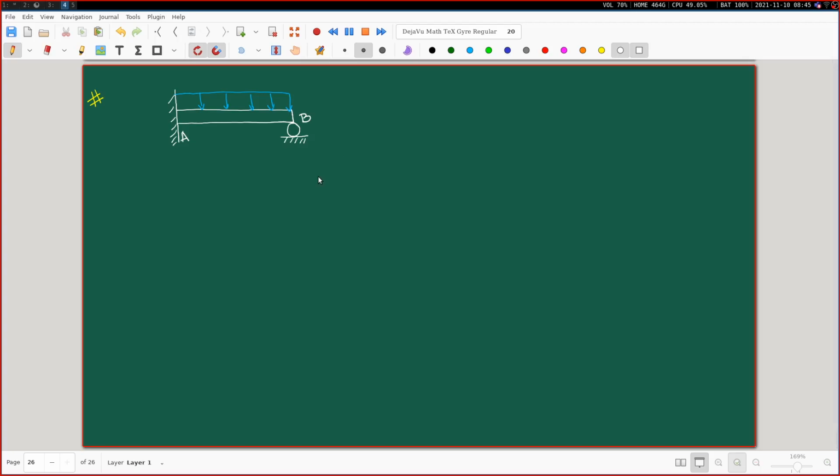So, what he said is like this. Our interest here is to find out the reaction force at this point. I mean, we want to find out all the reaction forces, but since we do not have a direct method, this is the problem situation. What we'll consider is that we will remove this support. This support was creating a problem. We'll remove this support, and when we remove it, we have to replace it through an equivalent reaction force it was applying on this structure, and that is just the vertically upward force. Alright, so we have that vertically upward force.